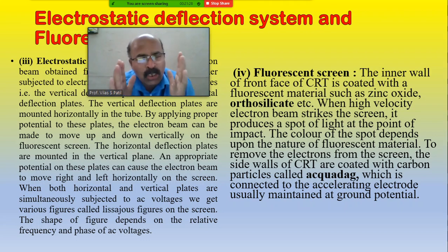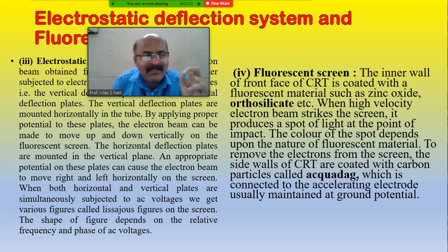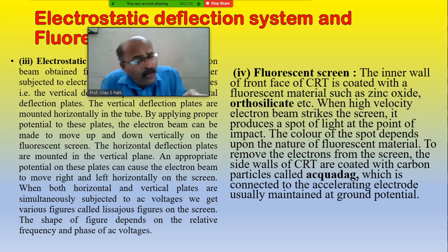And that shockproof development of the CRT will be made by this technique of the aquadag coating, and hence this fluorescent material is one of the best blocks of the CRT, and that will be used in the working of the CRT. And the role of the fluorescent screen is to produce the visual indication of the high energetic beam when it strikes the fluorescent screen.